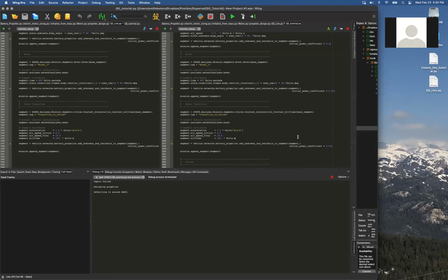For this case, the aircraft is also trimmed, so those things are kind of ignored. So the vehicle is trimmed in forces. It's not trimmed in moment. We didn't do any control surfaces, if you noticed. This aero model, because it's a post-stall aero model, is not that great to incorporate control surfaces or anything like that. So it's only trimmed in force, but not in moment. Right, so you would need to add another level of fidelity onto this to get the control surface deflections.